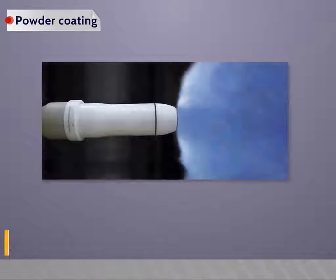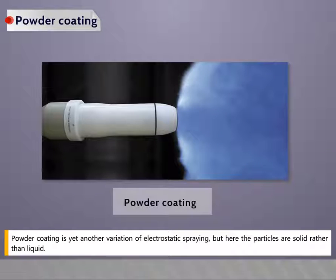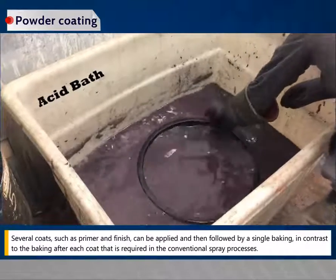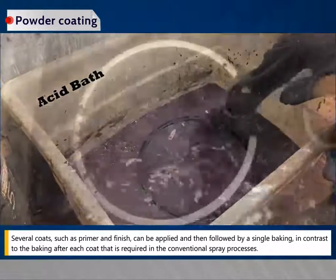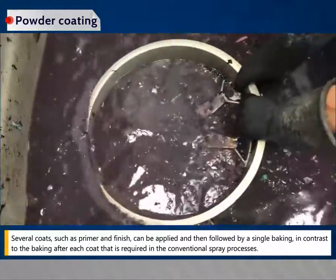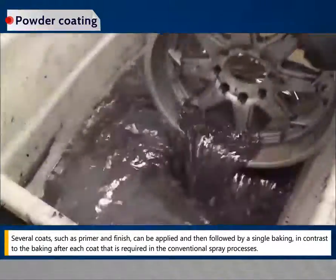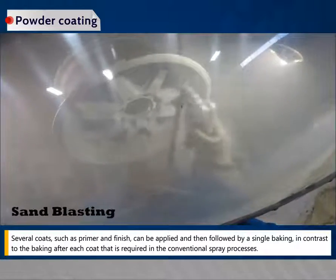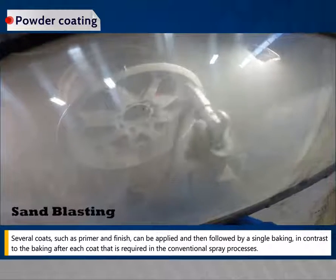Powder coating. Powder coating is yet another variation of electrostatic spraying, but here the particles are solid rather than liquid. Several coats such as primer and finish can be applied and then followed by a single baking, in contrast to the baking after each coat that is required in the conventional spray processes.